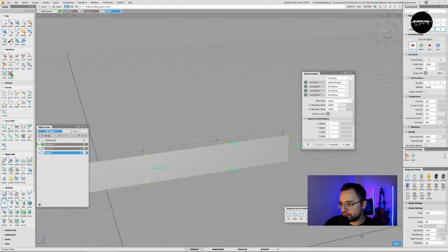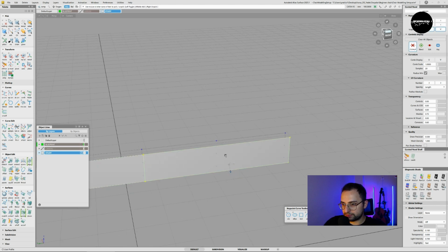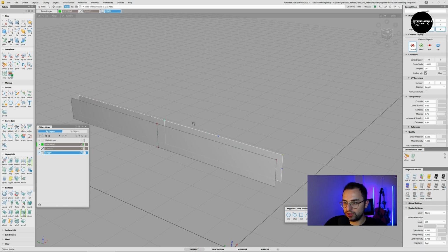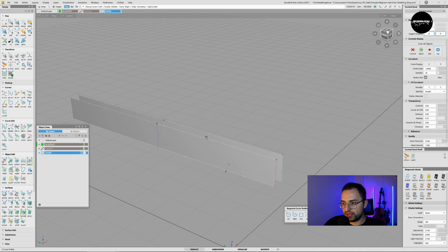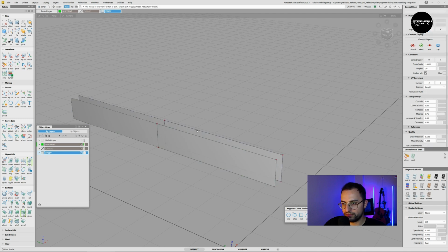So say next, and I am picking this surface, set pivot to that here, and copying, pasting it and moving to there. So we don't need to create another square, we already have it. So let's hide unselected again, display, hide unselected, so that we have only the surfaces.